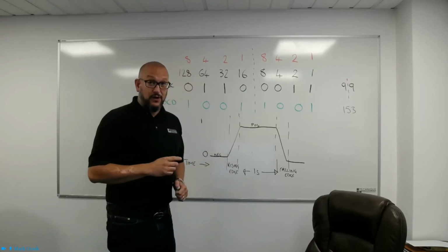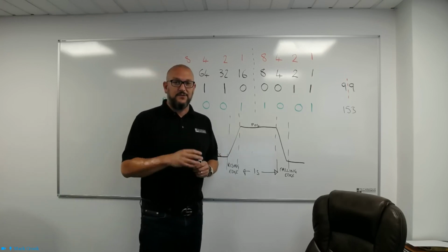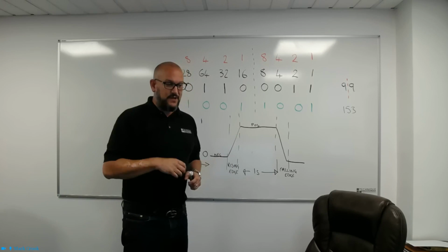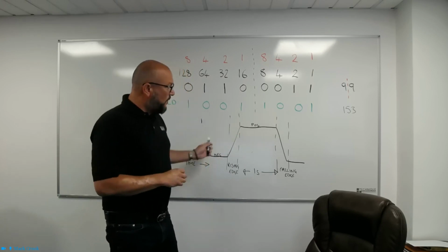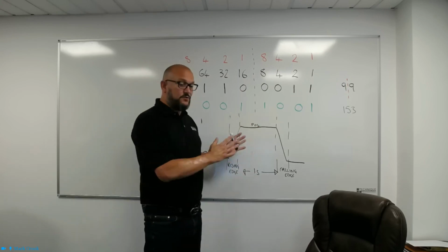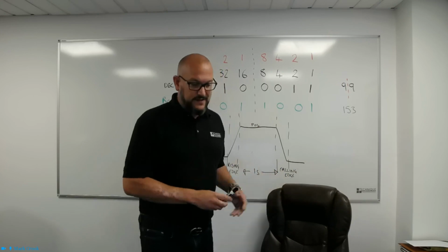So therefore, the maths command will have added or subtracted, or whatever command you're using, 50,000 times, and we'll see a massive ramp up in the numbering system. So we need to take that into account, and that's not just Allen Bradley PLCs, that's all PLCs that always work on the positive edge.